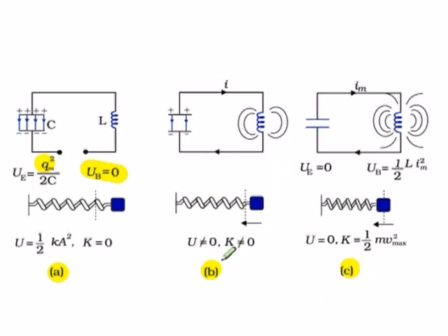B represents the status of the tank circuit at any time t between 0 and T by 4. As you can see, the capacitor has partially drained out, because there were 4 pluses and there are only 2 pluses here in the second figure. So part of the charge has flown, and hence there is a partial current I, which is less than I naught but greater than 0. In the previous figure, I was 0, now the current is some I between 0 and I naught.